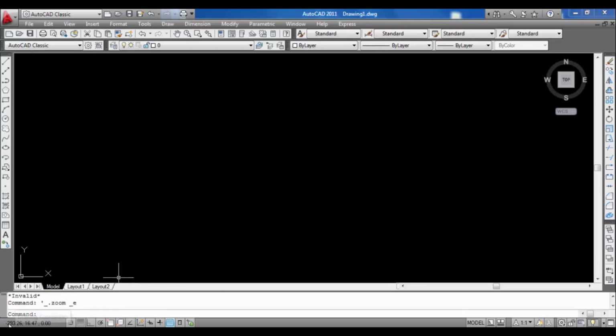Now our coordinate system changes in millimeter. If you move this cursor or pointer here, you can see the value of the x and y coordinates. Now this is our working area. At present we have not taken any command from the draw menu or from icons, so my pointer is like a cross with one square at the center.